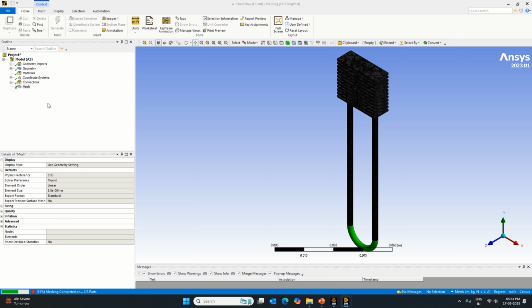Definitely, if you take it 0.005, the time requirement will be on the slightly lower side. But there may be chances of a floating point exception error. Because especially the fluid zones are involved, we might be more interested in making it better, especially on the fluid zones.